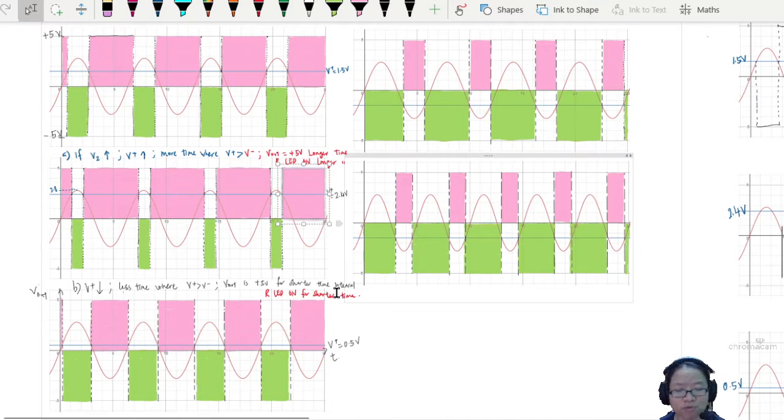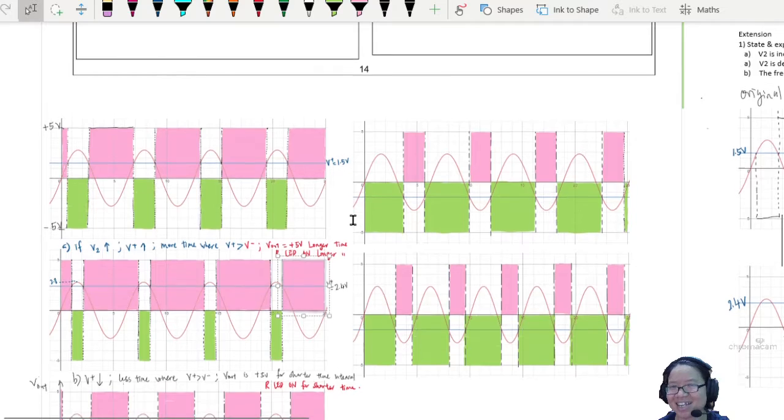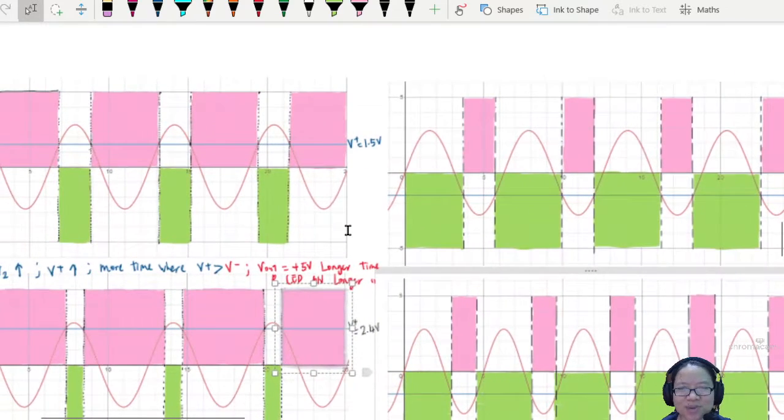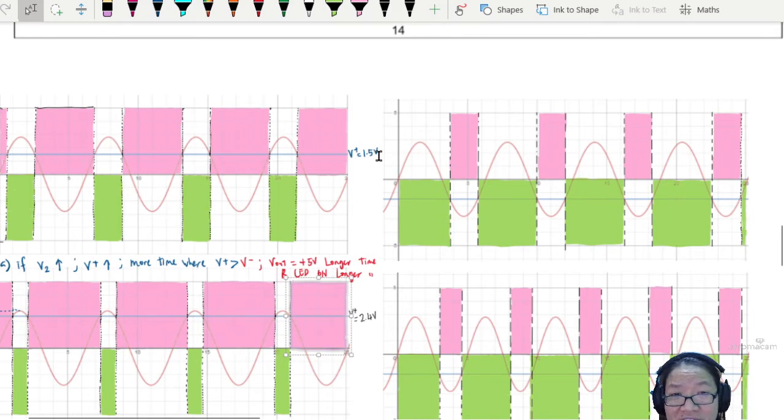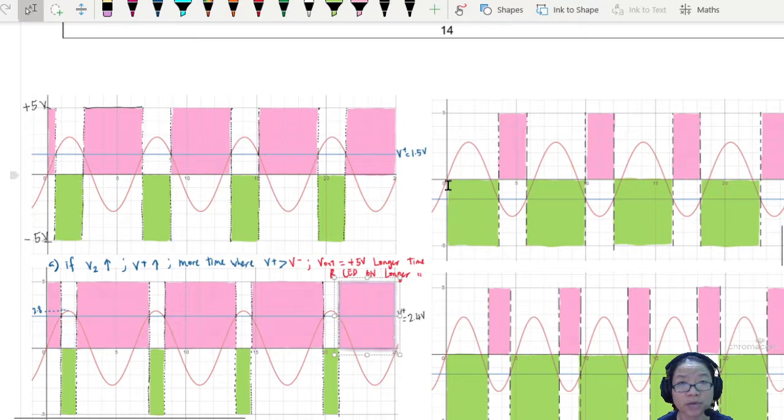All right. And then this is a bonus for you. Because remember, I sneakily said I don't have to think so much. You go and take out the battery, the power supply, or the potential divider. Because this 1.5 volt could be supplied by a potential divider. Okay. So later we'll discuss some examples where we use a potential divider to choose a set voltage. Because in this circuit, they didn't actually tell you how they put this 1.5 volt. They could connect this to a battery. Okay. They could connect it to a potentiometer. A potentiometer is always more stable than the battery.